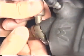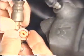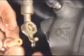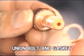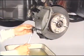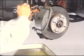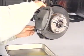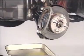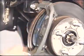Remove the union bolt and the 2 gaskets from the brake cylinder. Prepare a container to collect brake fluid and remove the flexible hose. Grasp the sliding pin and remove the fixing bolt and cylinder from the torque plate. Remove the 2 brake pads.